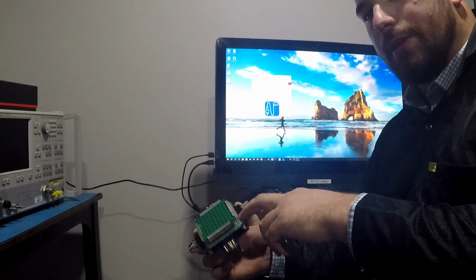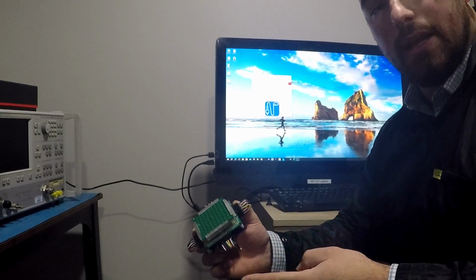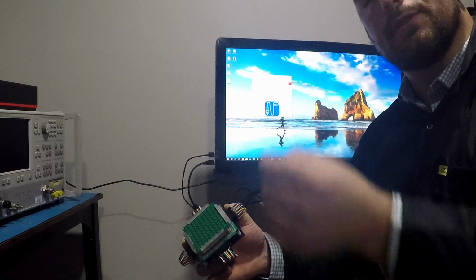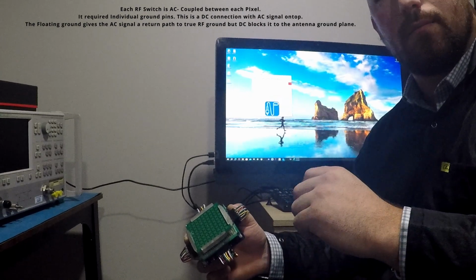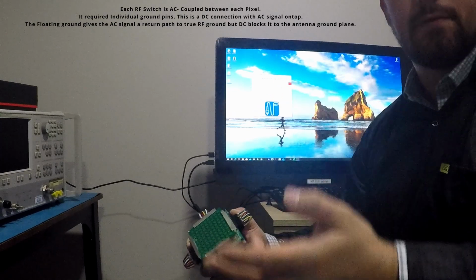For this geometry, there's 3 grounds to it. There's a true RF ground, true DC ground, and then there's also a floating capacitive ground for the RF switch to have a ground return path, because the DC ground and the RF ground can't be fully connected, or else the RF switches won't work. So there's a floating ground.